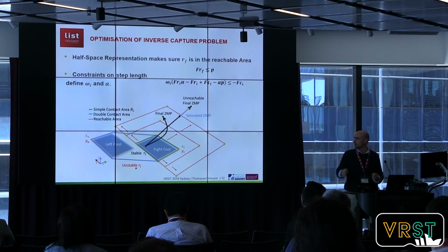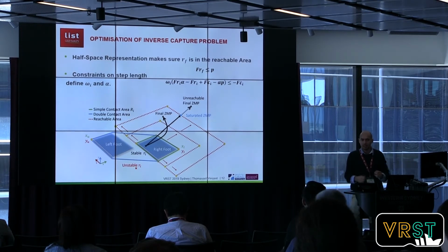If it does, then I'm moving the foot to that position, and if it can't, I'm increasing the range of the step. I'm saying, try to find a solution for a longer step. And I'm doing this iteratively until I find a solution, or until the system says I can't reach farther. I'm doing the biggest steps I can, and yet I can't find a stable position.